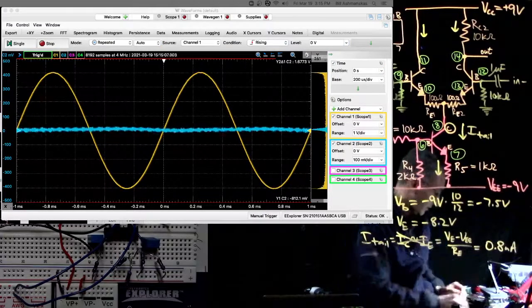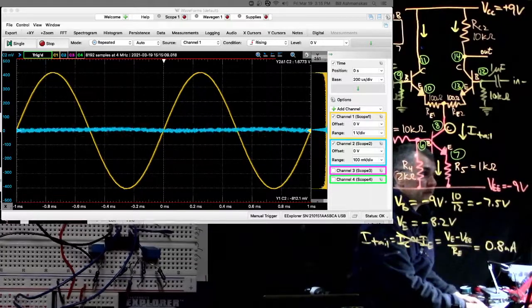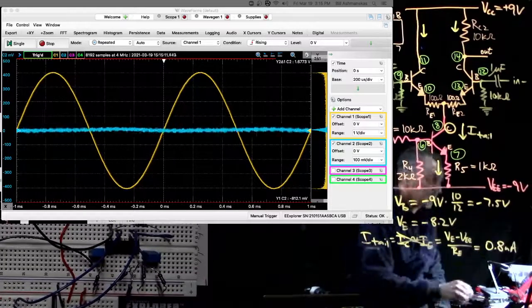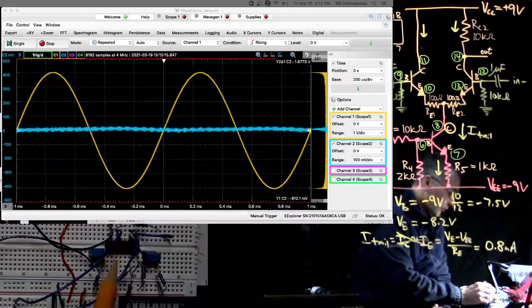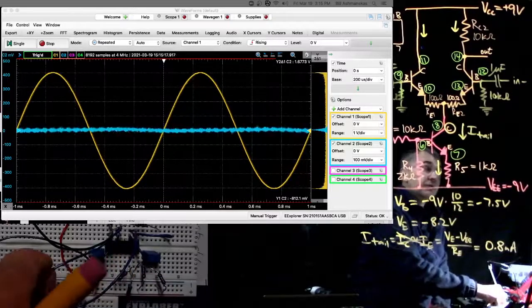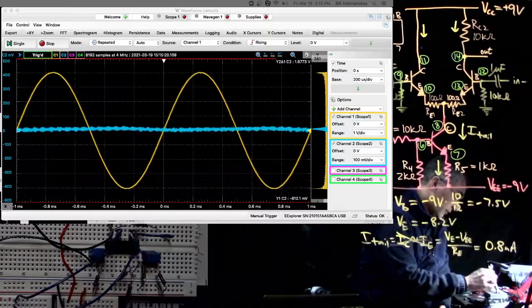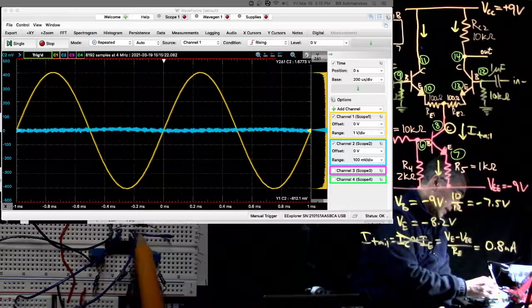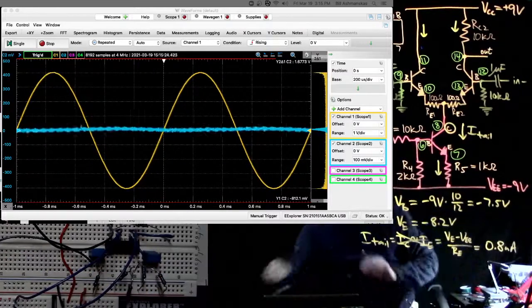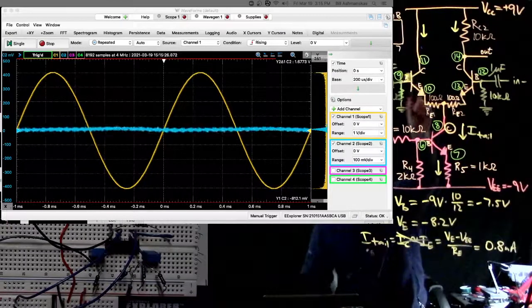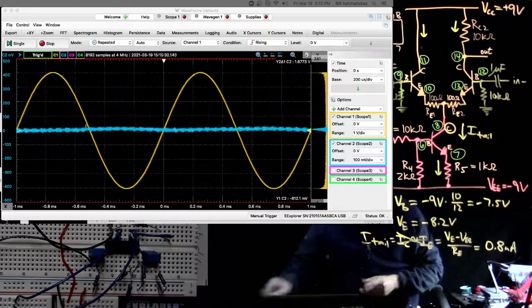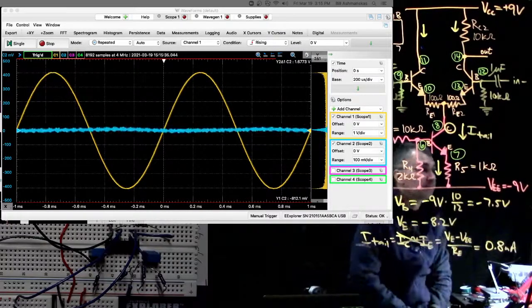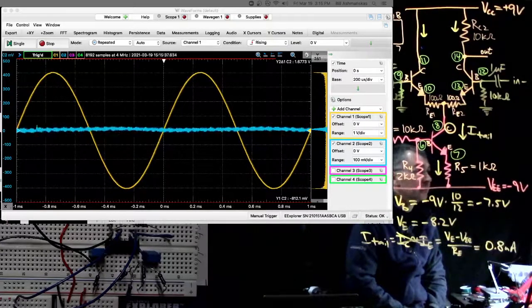How am I going to do that? There. Right. So one of them I put into pin 12 up here. That's over here. One of them I put into pin 9 over here. So I basically plugged them in directly to the two bases. And then that seemed to get me a much more exactly balanced common mode signal.